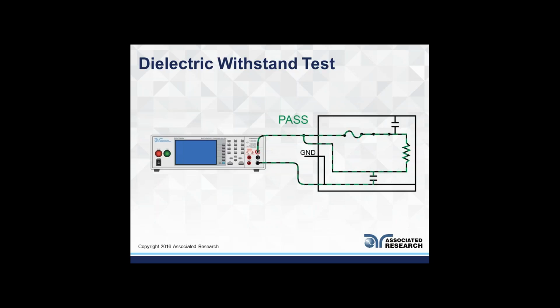There are some products that we've seen that could go up to 80 or 90 milliamps. This does not indicate a bad product. It could be just the nature of your product. What the standards usually look for is breakdown happening in your product.